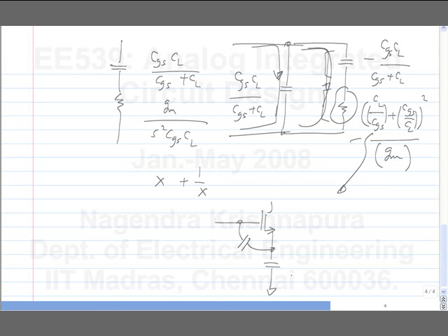If I have a very large GM and a large skew between CL and CGS, you can get the same effect as a small GM and CL by CGS close to 1. Of course, it is efficient to use a small GM, which means a smaller power dissipation, and a CL by CGS close to 1 when you want to make a negative resistance. When you want to avoid it, you want to make sure that either the load capacitance is very small or CGS is very small.